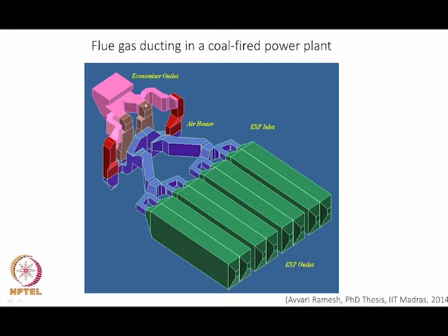And then as it is coming through this at some angle, again it has to split through this, and the flow rate through this and flow rate through this are not necessarily the same. These depend on the process requirement, how much heat you want to give to this secondary air preheater, and how much you want to give to this primary air heater. So, that means that it cannot be tackled in a simplistic way. And you need to accommodate these air preheaters, and you have ducting which is bringing flow into this and separately into this, and then those are happening.